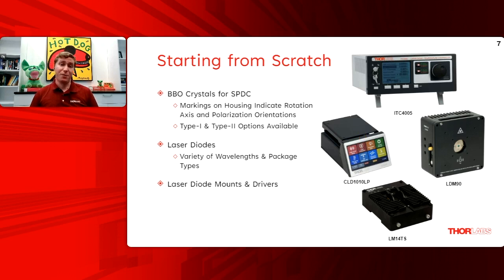That is going to be for the butterfly diodes. So both of those different styles, or drivers rather, are going to be all-in-one solutions. So you'll put in your pigtail TO-CAN, your butterfly, and you can control the current, you can control the TEC. Really, it's just ready to go off the bat.